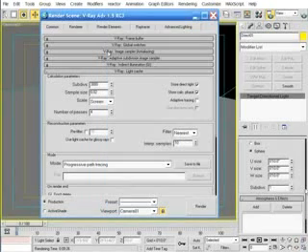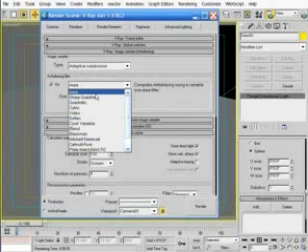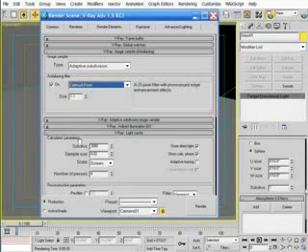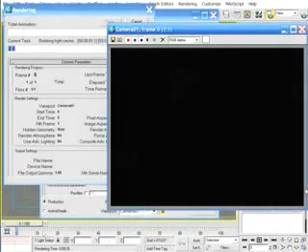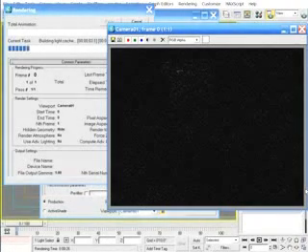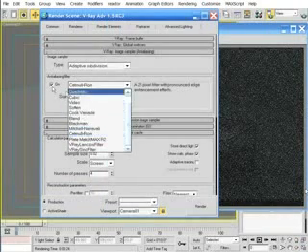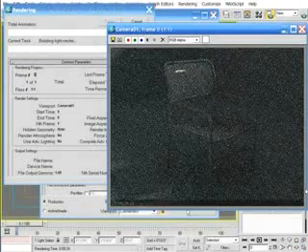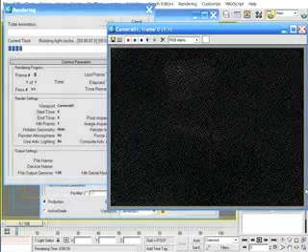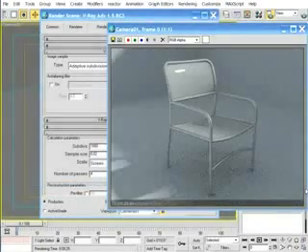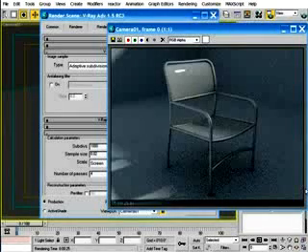Also, the anti-aliasing filter plays a large role in the noise that appears in your rendering. Using a filter such as the default area filter will produce nice renderings, but very sharp filters like Catmull-Rom or very blurry filters such as the soften filter will add a large amount of noise and should therefore never be used. Your best choice would be to disable anti-aliasing altogether, and by doing so you'll still get anti-aliasing, but it will be handled within the light cache algorithm, so your final rendered image will still look fine without this option enabled.